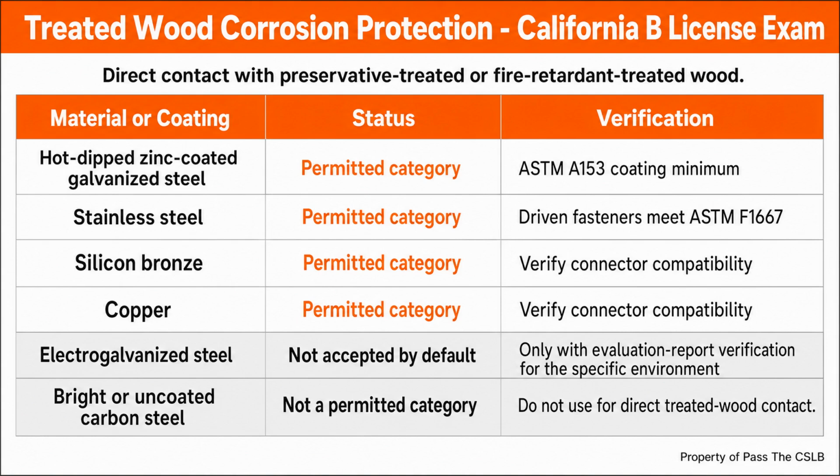The second pass happens during a small initial installation. I check orientation, designated hole groups, nail angle, fastener type, and whether the tool is placing the correct fastener without altering the connector. I would rather correct one sample bay than discover the same mistake across an entire floor.